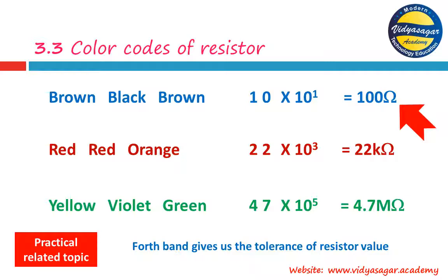So every manufacturer gives the tolerance value. They give you the idea that this resistor might have this much error. So for this resistor having a golden band at the fourth position, the value may be from 95 ohm to 105 ohm. So such resistors have 5% error, and they can be used in our general purpose applications.